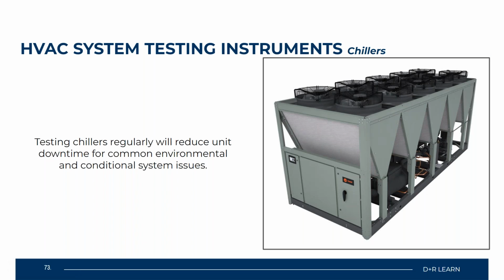You also want to test your coil integrity through eddy current testing. We just spoke about that in water-cooled applications. Check for pitting, any type of corrosion integrity of piping within the exchanger. And lastly, for your chiller systems, you do have pumps associated with them. You want to do a motor integrity check on the electrical connections. You want to verify free operation of that pumping system without obstruction or mechanical failure. And also, you want to use a multimeter for the motor to check the voltages and amperages, and a tachometer for rotation. Tachometers we'll touch on shortly, which check the rotation of your motor system.